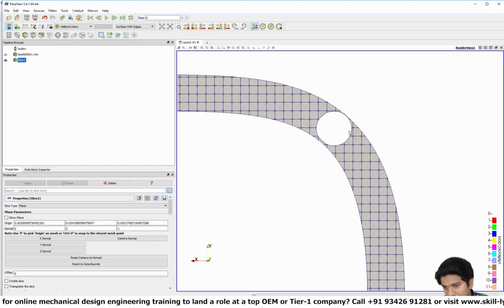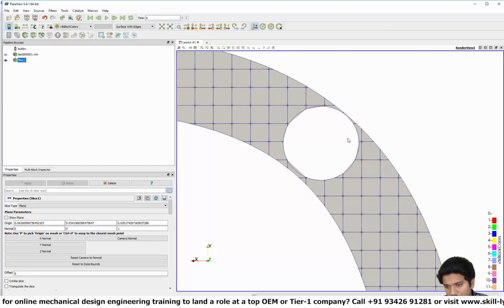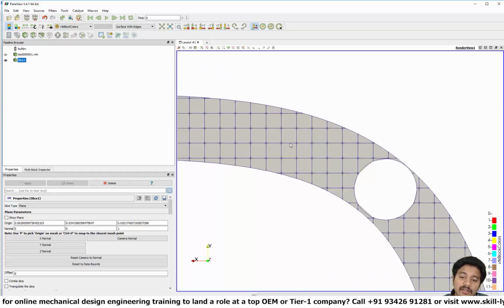And here you can see that if I want the flow to go on top of the throttle plate and in the bottom right, I need at least a few cells. The meshing technique that Converge uses is called a cut cell Cartesian method. So you can see that no matter how big your base grid is, we actually cut the surface using our cell.